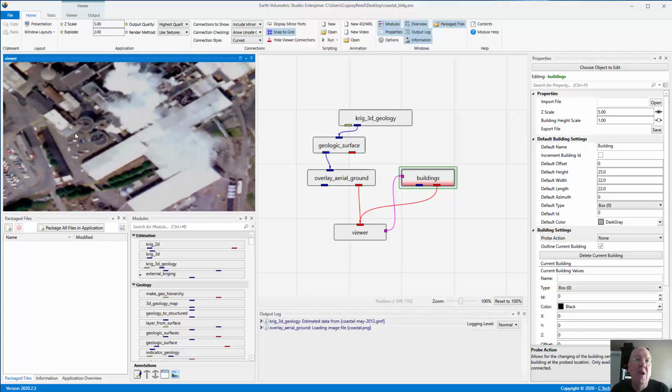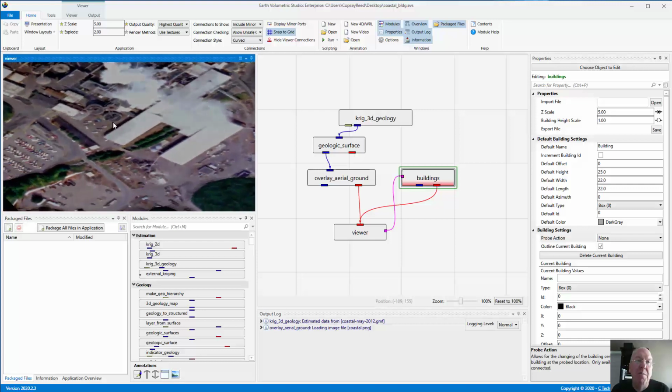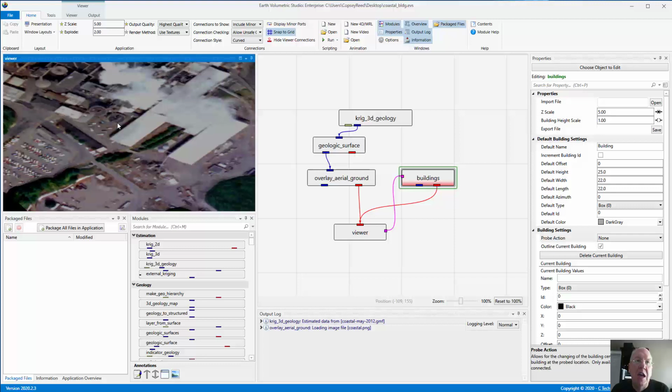And so very often you've got a vertical scale for your geologic layers, but if you created the buildings with Z-scale 1 and you scale the buildings, they'll start to look ridiculous. In other words, we all have a good knowledge of what a building should look like. We know that commercial buildings, for their large size like these, are going to be not as high as they are wide or long. And we know kind of what a tank should look like. These tanks might be 2 or 3 times as tall as their diameter at most.